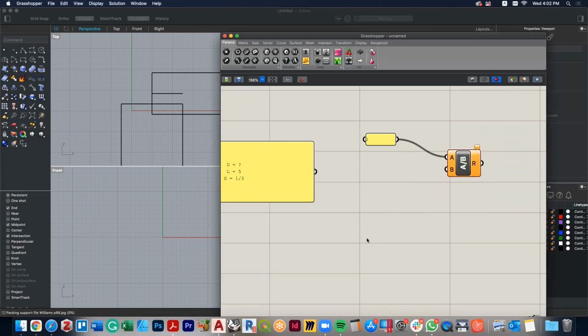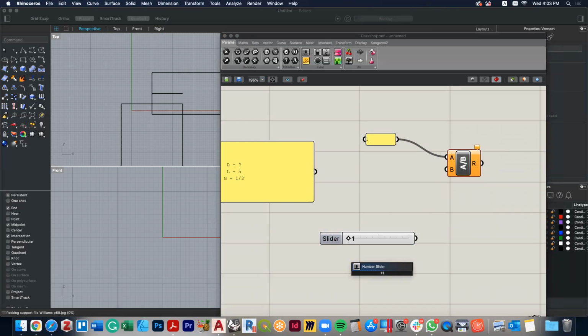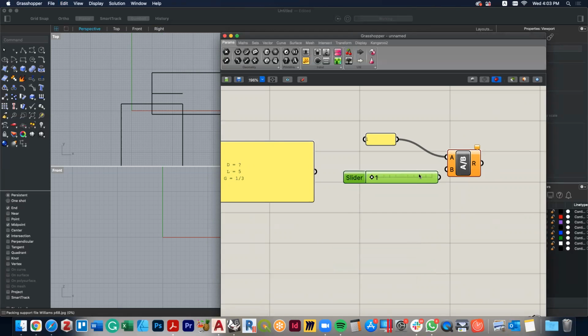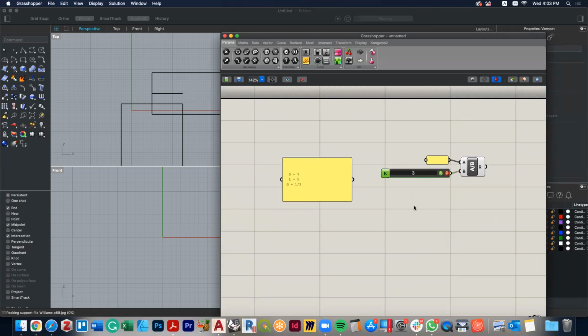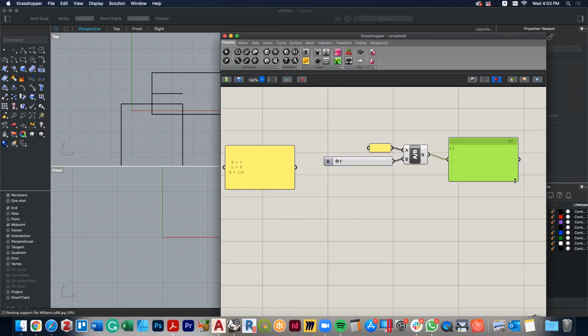And now I'm going to create another thing. So I'm going to go 1 to 100. And so this is now my grade calculator, my decimal grade calculator. Because it's 1:3, you notice that syntax again, right? 1 in the smaller than whatever the number might be gives you a slider of that value 1 to 100. And then I'm going over here, and I'm basically making that 3. And then I can put a panel on the other side, and we can see what that percentage is.